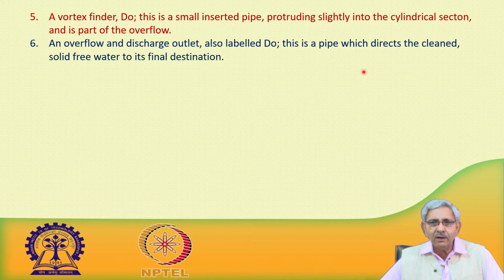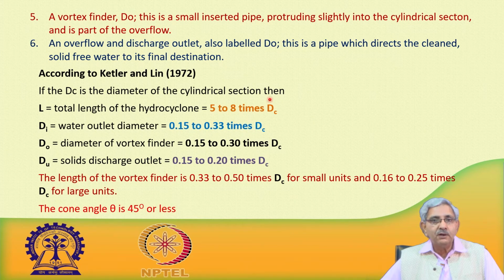So, one can decide the dimensions, that is, what should be the capacity of the filter system. So, that will be decided depending on the quality of water, means what is the percentage of the heavier particles or large size particles which are available in the water, and then what is the size of the pump where the flow is taking place. So, discharge of the pump is also considered.